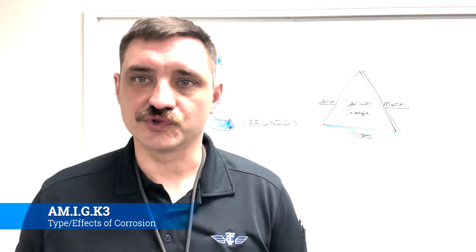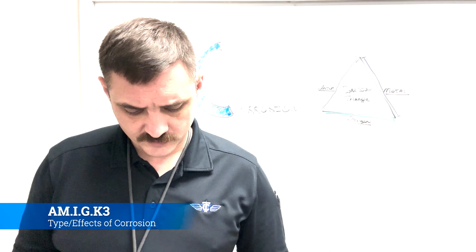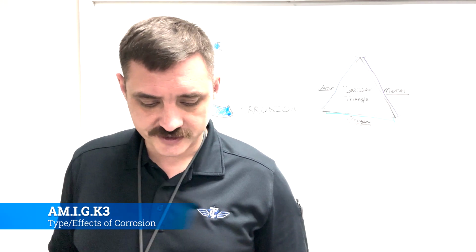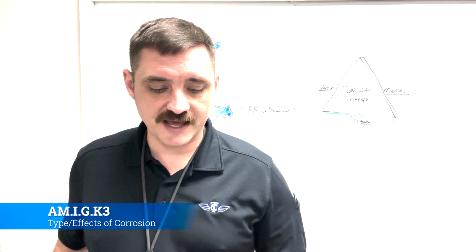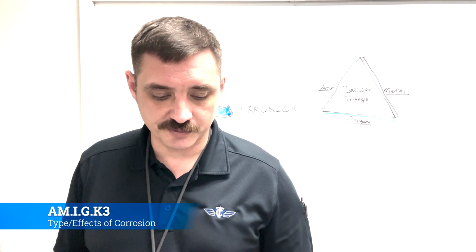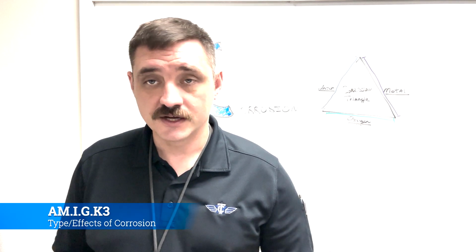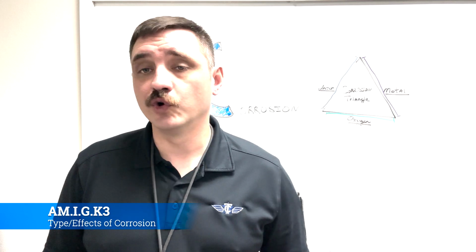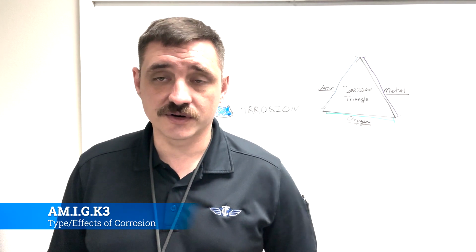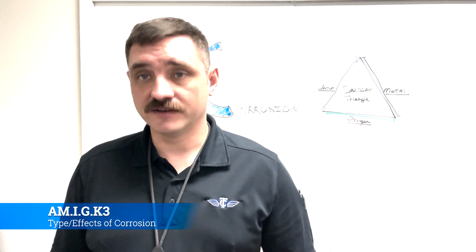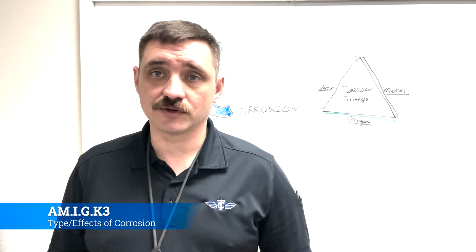And you can go find an old truck or whatever, run your hand on it, so super rough. Okay, dissimilar metal corrosion is extensive pitting damage that results from contact between two dissimilar parts in the presence of a conductor. So essentially you would have aluminum and iron that are touching one another, and then they get wet, and then you'll end up having dissimilar metal corrosion.